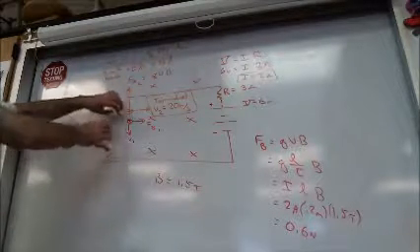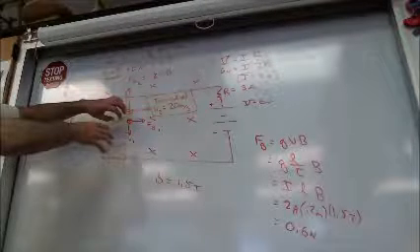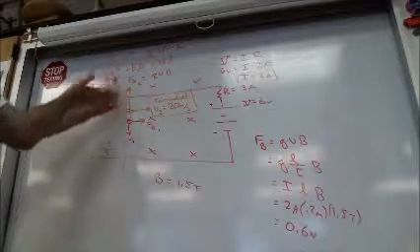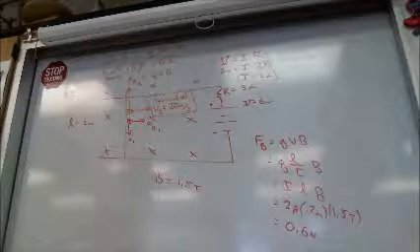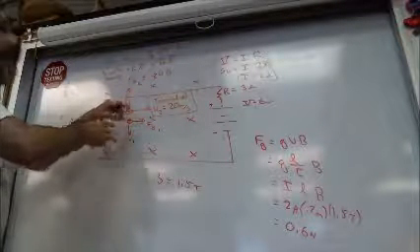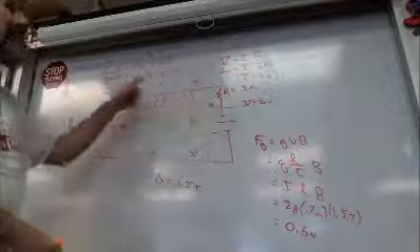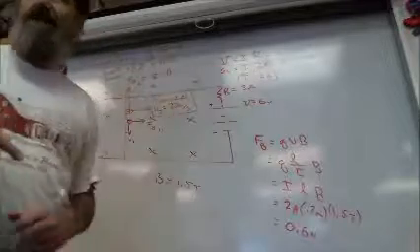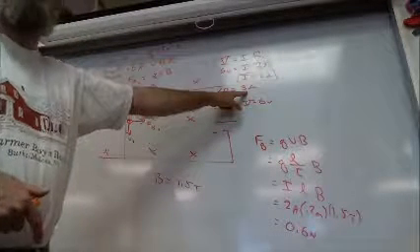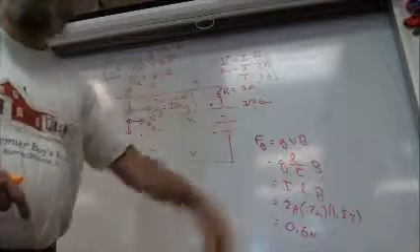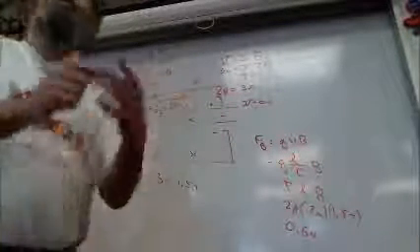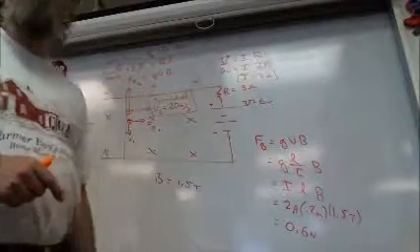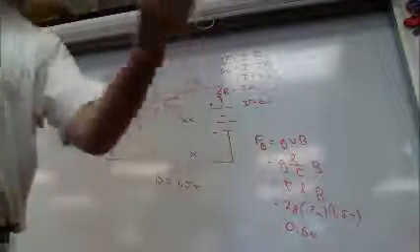If I stop this thing from moving, then there won't be any velocity to generate this back force. You get it? So if I stop the drill from moving, there won't be a back EMF, and I will be at maximum current. The current initially was 2 amps, right? Imagine if that resistance was like 1 ohm. My current would be 6 amps. What if my drill has very low resistance when it's not under load? Maybe it's 0.1 ohm. I could end up with a lot of current, couldn't I?